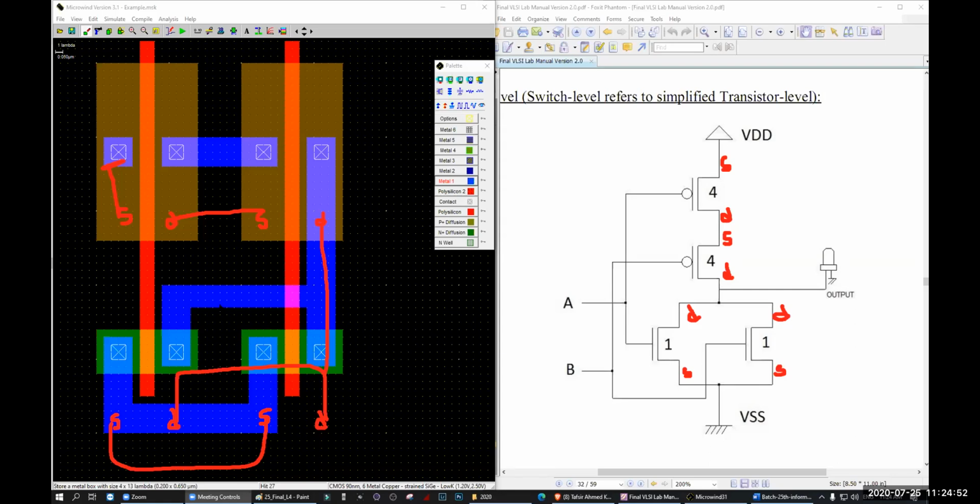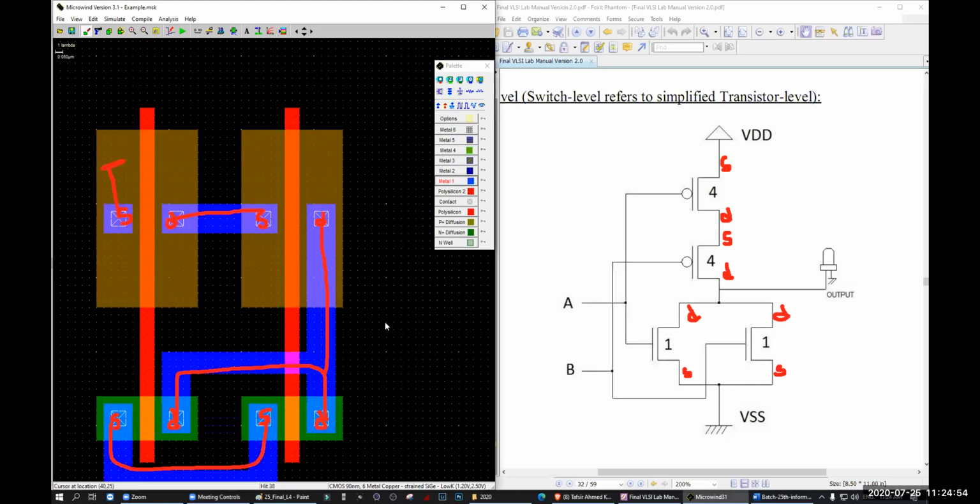Now we have already connected all of these. So this is the connection. Now what I'm going to do, I'm going to erase this thing. This thing is no longer required. That means these are no longer required. So here I will connect my VDD. Here I will connect my output, because the connection between PMOS and NMOS is our output point. And here we will connect our ground. See, the source is the ground, right? Yes, sir. Okay.